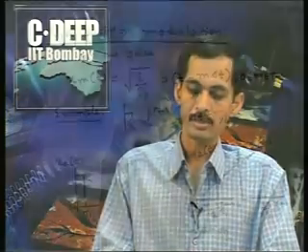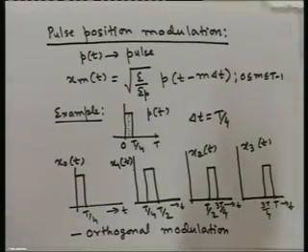And what will that mean in terms of bandwidth? If you take a narrower pulse, the bandwidth of that pulse actually doubles. So if we increase the number of points by a factor of 2, then we actually increase the bandwidth used by a factor of 2. So we can see that bandwidth increases proportional to the number of points M. And again, energy and minimum distance both can be kept constant while increasing the number of points.